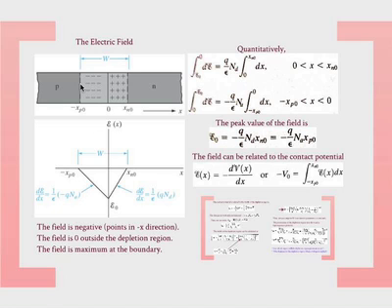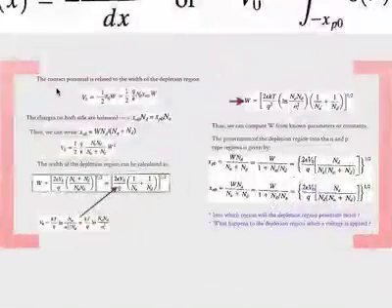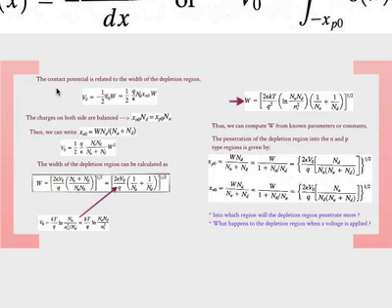And the field, of course, is pointing from the positive charge to the negative charge. It is preventing the diffusion of the carriers. Okay? The holes try to diffuse from P to N, the electrons try to diffuse from N to P, and they're trying to balance, the built-in field tries to balance that out. So that's the equilibrium situation. Okay? And then we calculated what the contact potential is, based on which we can relate to many things.